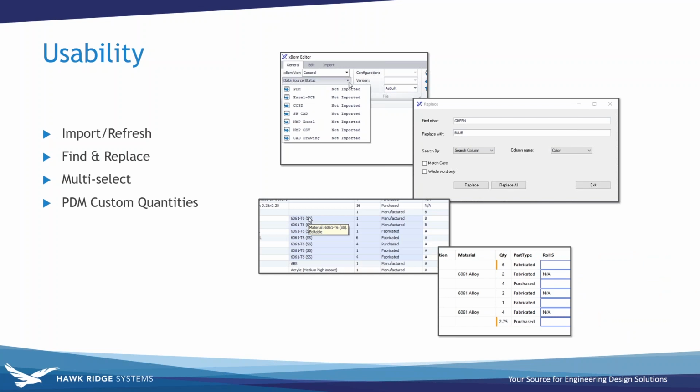And then one of our more recent additions is that in PDM, when you have an assembly checked out, you can go to its bill of materials, this computed BOM, and you can manually modify quantities. And this can be important if there's manually attached references, data sheets or anything else from your vault.